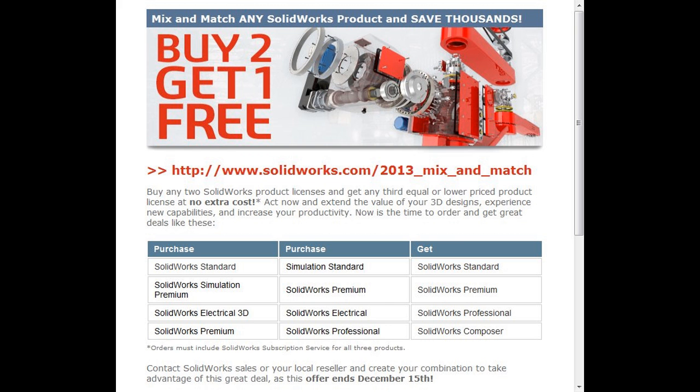How do you get the extrude above the revolve on the second model to extrude down to the cylinder as well as out? I think when I created the first extrude, I had the revolve first, then I created the first extrude. In order for it to go all the way down, maybe I wasn't clear, I chose the same rectangle that I used to revolve as a region for the extrude. So the entire shape, I extruded it out, not just the top half. So hopefully that was clear. Again, if you go to the forums and take a look at some of these, you'll see these models are all up there. There'll be a video of how that one was done as well.